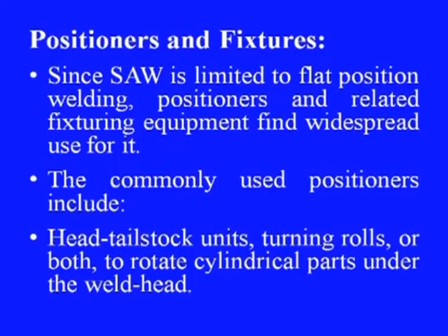Next components are positioners and fixtures. Since submerged arc welding is limited to flat position welding, positioners and related fixturing equipment find widespread use for it.